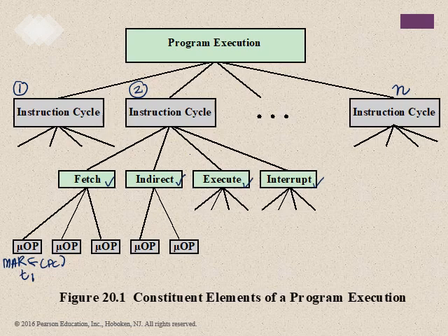And then we have the next micro operation, memory goes to MBR. And at the same time, because it uses a different unit, we have the content of the PC, we add 1 and we send it into PC. So the first micro operation is at T1, and these two micro operations are at T2.